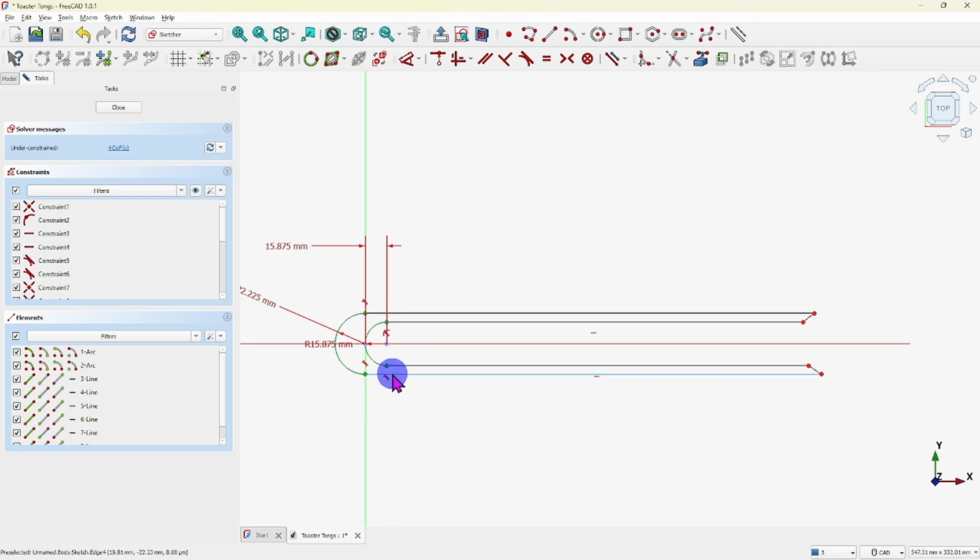So the distance vertically from this X datum line, these lines are already set by those radiuses, so we don't have to dimension from the X datum down to these lines individually, at least I don't think, but let's get into it and see if it makes us do that. But if I did this correctly and these lines, these endpoints are joined to each other, then I should not have to do that.